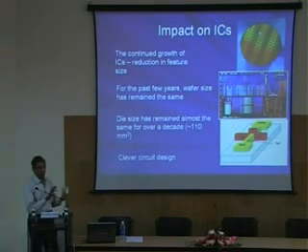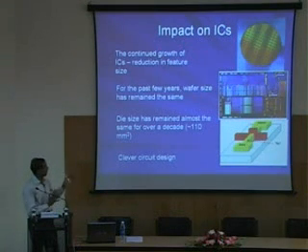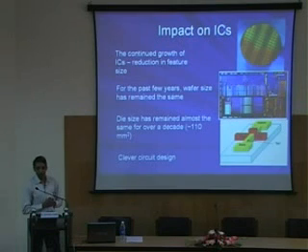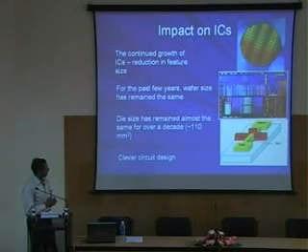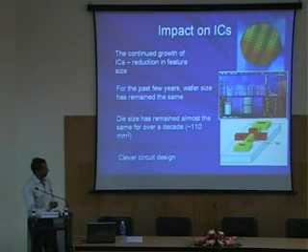We are stuck at around 18-inch size wafers. You can't really go beyond that. And the die size also has remained at around 100 millimeter square. And we have also almost reached saturation in terms of our cleverness in designing these circuits. So we have almost reached a saturation point. Now, if you want to further push the silicon technology beyond this point, if you use the conventional devices in order to push your silicon roadmap, it's going to be extremely difficult.